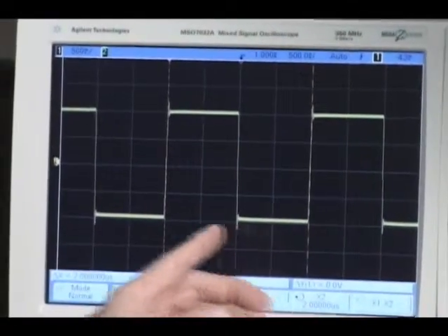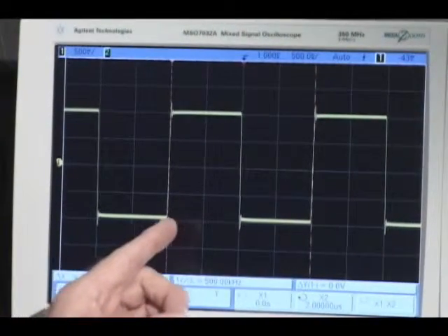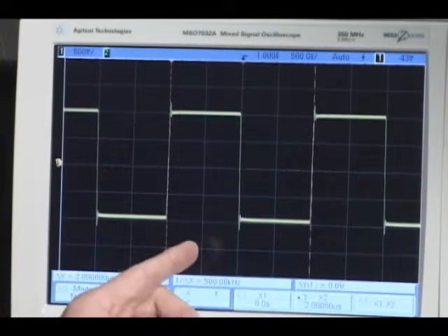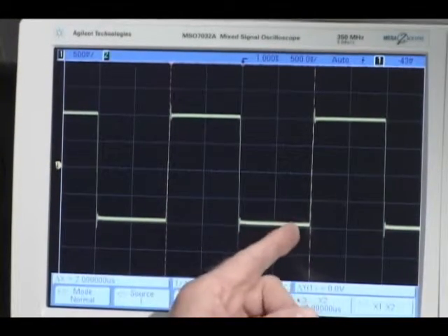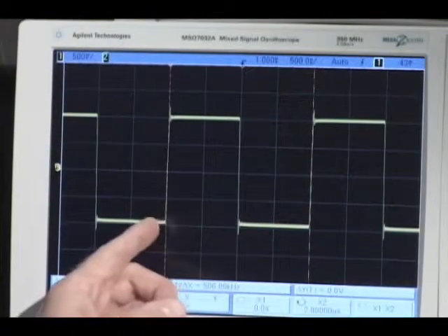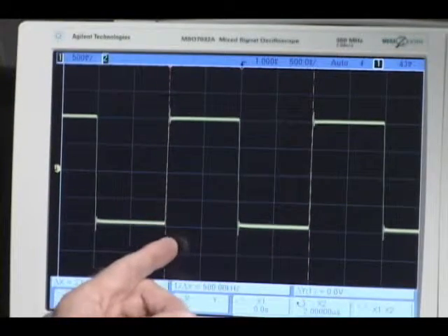Again, if we pan back over to the scope, what we have done by setting the gate hold off is we've prevented the gate from closing until the conditions of the close, which are the positive edge, have been satisfied, those occurring on the next rising edge, therefore giving us a measurement of the signal period.